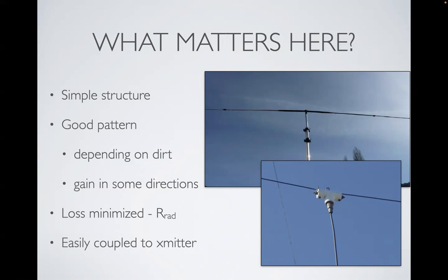Remember what we're trying to do with the transmitter. Transmitters that we build in ham radio are really happy when they're feeding a 50 ohm load. If you want to make your transmitter happy, you coerce whatever you're driving into 50 ohm resistive, and then the transmitter will be very happy. It's not a matter of energy transfer. There's a lot of incorrect thinking, in my opinion, around things like the maximum power transfer theorem. I have another talk where I dip into that one, but it has a certain assumption that's not true when we think about things like this. The thing you really want to worry about is just making the transmitter not get hot and be happy to drive that load.